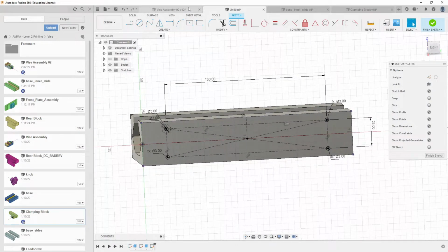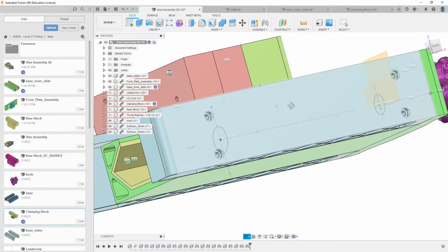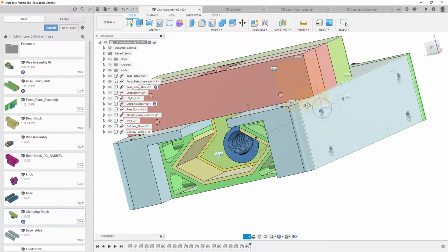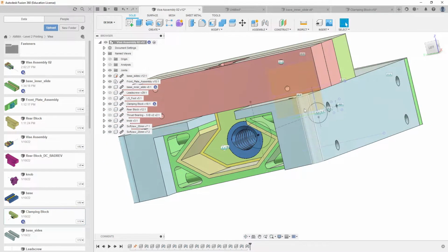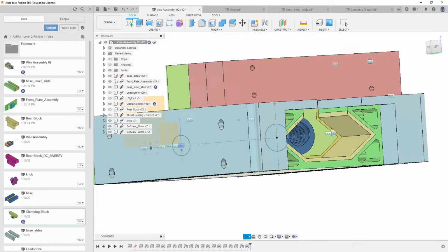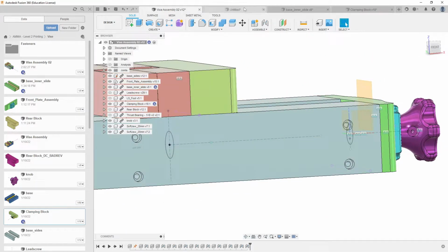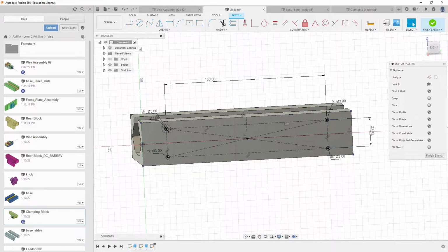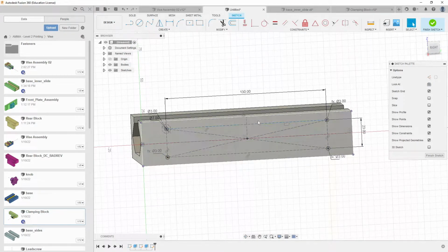Now when I go to do those holes in this side block, my edge margin is not going to be the same. I can get it to work, but when I went to do it, I said, let's find the edge margin first, and then measure what this is and make it this. So now I just remember 130 by 23. I could easily see going the other direction with this, okay? I did it this way because I felt that later down the road it might be easier for me to remember 130 by 20 based upon the center of this thing.